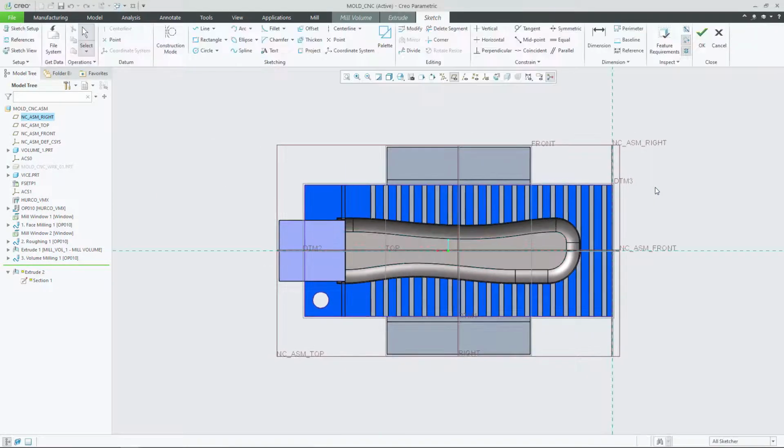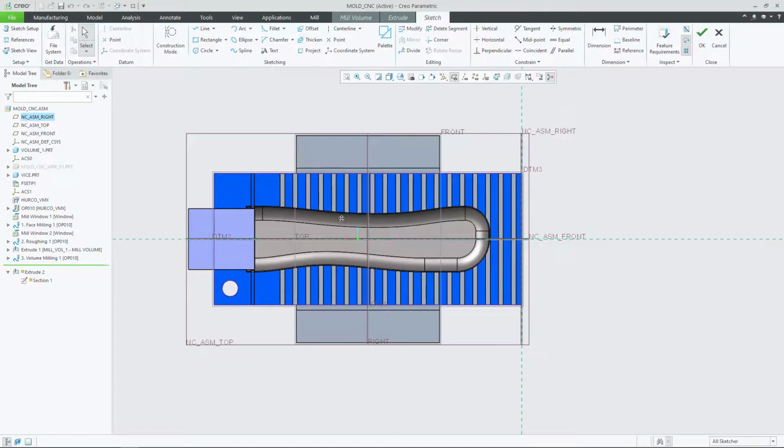Yeah, that is fine. So now I'm not actually going to manually create this shape in this sketch. I'm going to steal some geometry from the reference model itself, so from the mold itself. So I'm going to use the project tool, which we've used many times before to copy geometry into a sketch. So project, and it's a loop that I want to copy into this sketch.